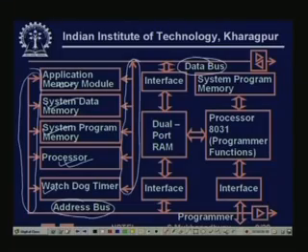PLC systems are special. You must have experienced that sometimes your PC hangs, it just sits quiet doing nothing. Somehow it gets mired into some kind of infinite loop. This is prohibited in PLC systems, if due to reasons like wrong programming or memory corruption the processor stops doing useful work, then there have to be explicit mechanisms by which the processor execution is brought out of it and taken into a safe state.